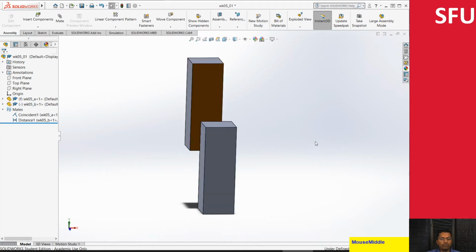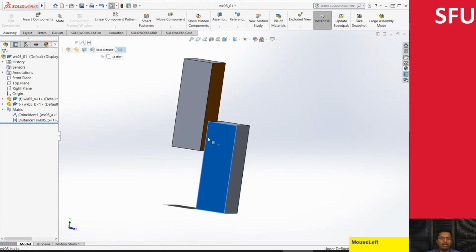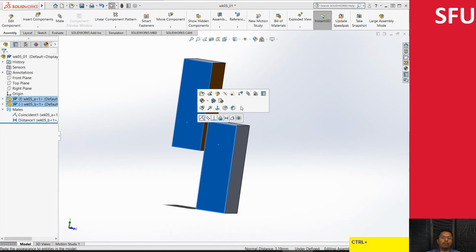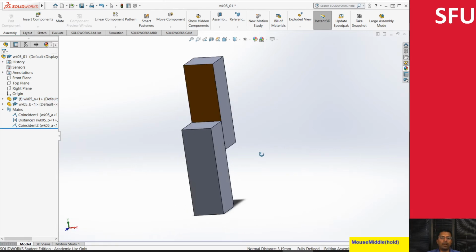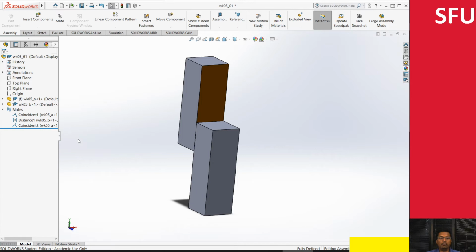We have these two. Now let's say this and this part, and then the only thing left to do is make it coincident, and this moves the object, and now everything is stuck together, and everything is perfectly assembled the way you want.